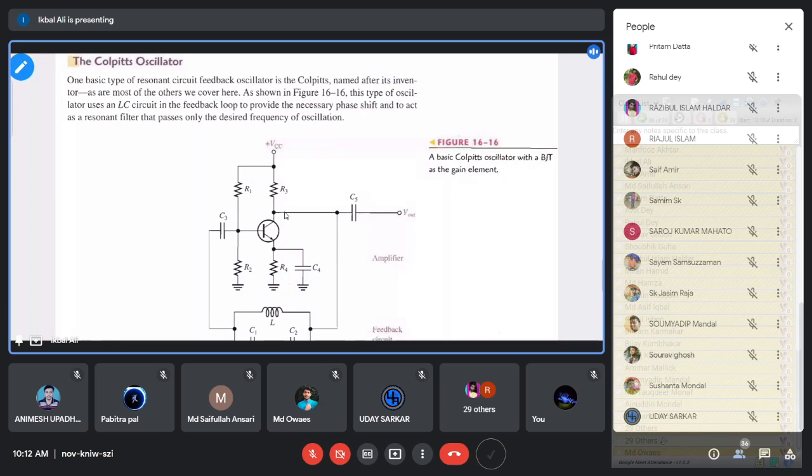That class of circuit is known as the LC oscillator. That means the beta network contains inductor and capacitor. You will see inductor and capacitor in the beta network, and no resistance. Resistance value cannot be minimized to a very small value. If you try to build a resistance of 0.1 or 0.01 ohm, that is meaningless, because that type of resistance, close to zero, is very difficult to build. That is why the RC circuit cannot generate a very high frequency signal.